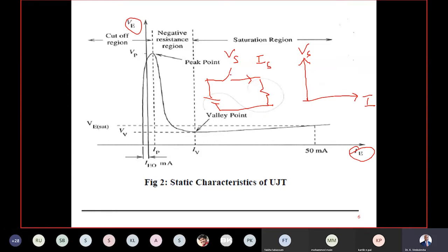Now, when the switch is in off state, what is the voltage available across the switch? Nothing but the supply voltage. Because of the open circuit, my supply voltage, say Vin, is available across my switch when the switch is in off state. So my voltage is maximum when the switch is off, but current is zero. That is why my point lies along the y-axis, because the current flow in the switch is zero.